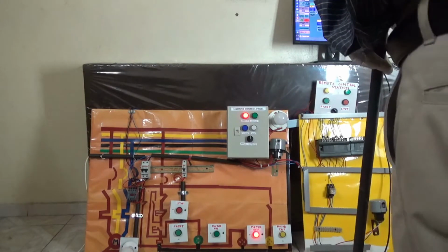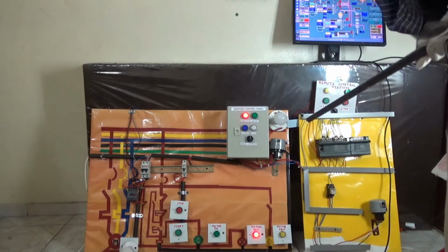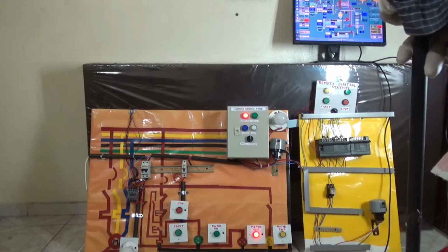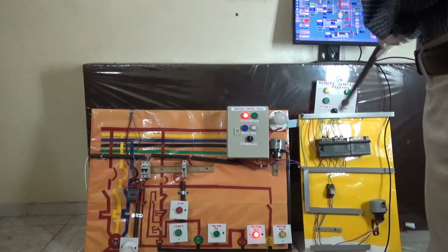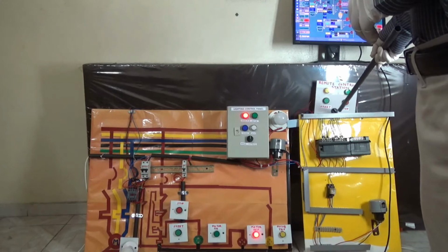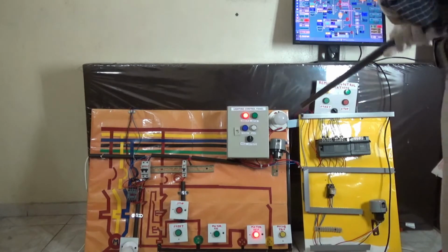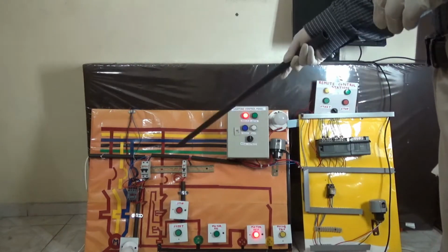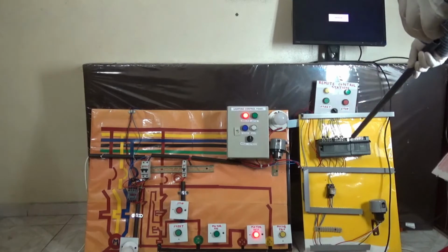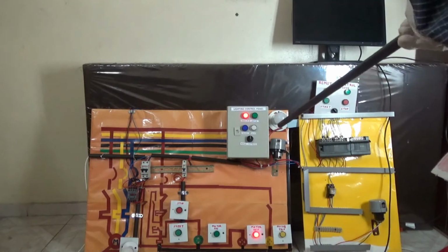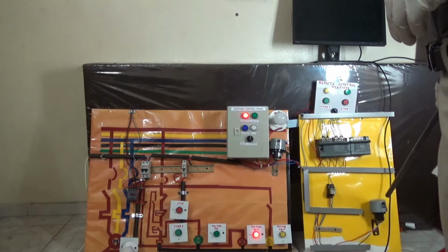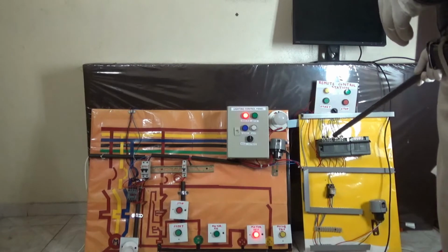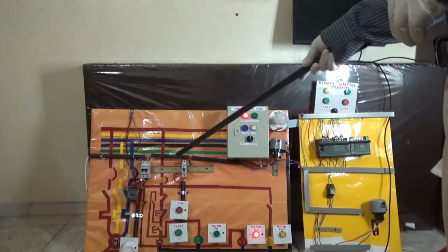Now this is called a programmable logic controller. It is used for automation systems. Now this switch is the manual auto switch. When we put this switch in auto mode, this motor or bulb will be controlled by this PLC. There is a sensor here. The sensor is connected to a relay, and the relay will give a signal to the PLC, and the PLC will switch on this light.